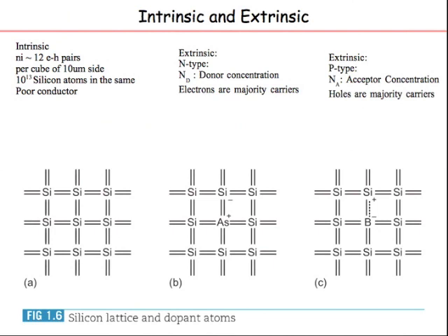But always, due to some thermal excitation, you'll have a few electrons which are free, and there's not that many of them. Now, of course, when you heat it up, you'll have more electron hole pairs formed, and so the silicon material becomes more and more conductive as you heat it up. Whereas a normal resistor, when you heat it up, the resistance goes up. In the case of a semiconductor, it actually goes down.